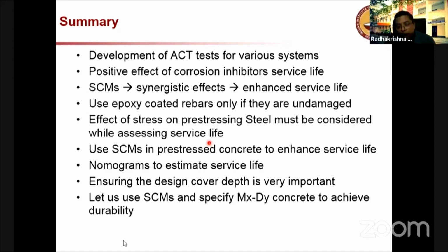Are you talking about the length of the steel or other factors? I think the question is from small size to large size of concrete. Yeah, with the larger size, you will find that the chloride threshold is also going to be higher, because essentially probabilistic function effects come into the picture.